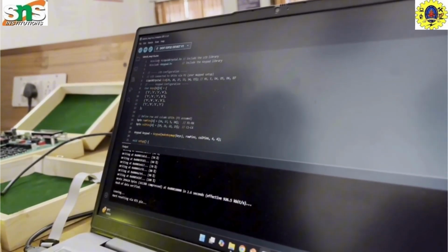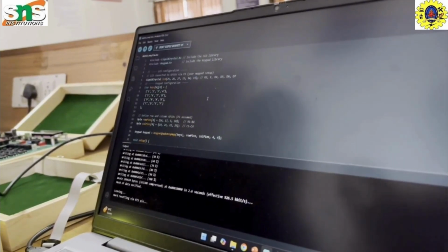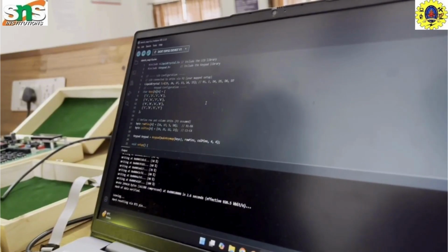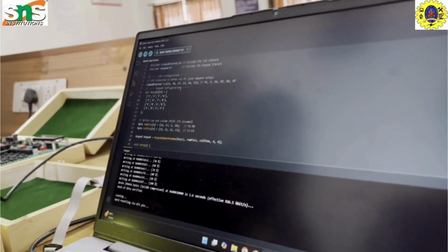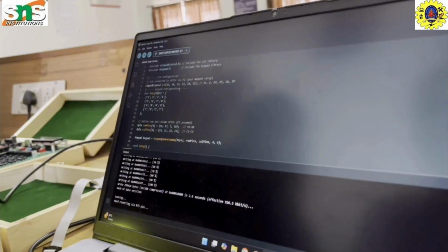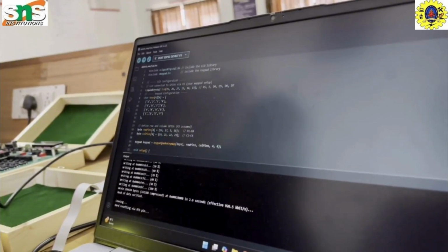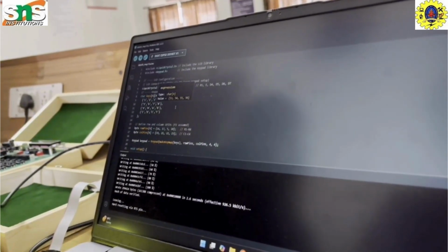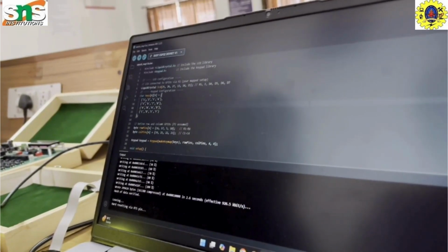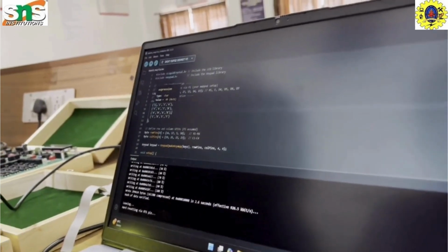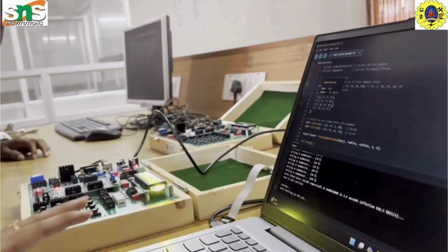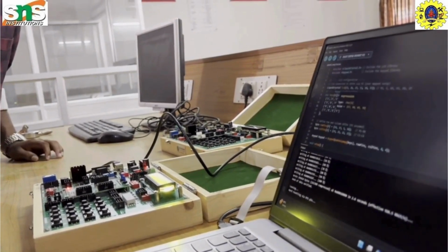So I am calling both libraries, and for the LCD screen, what I am going to define are the pins. These pins are the ESP32 configuration pins, and here I am going to describe the keypad pins. Here I have the keypad configuration like 1, 2, 3, 4. The exact keypad layout is given in the programming code, and next are the rows and columns.